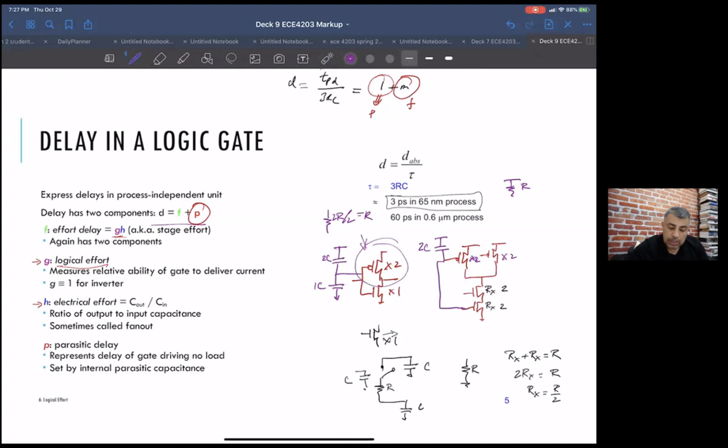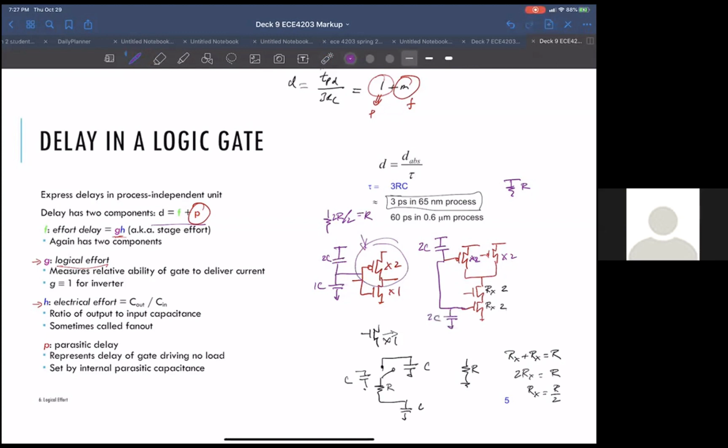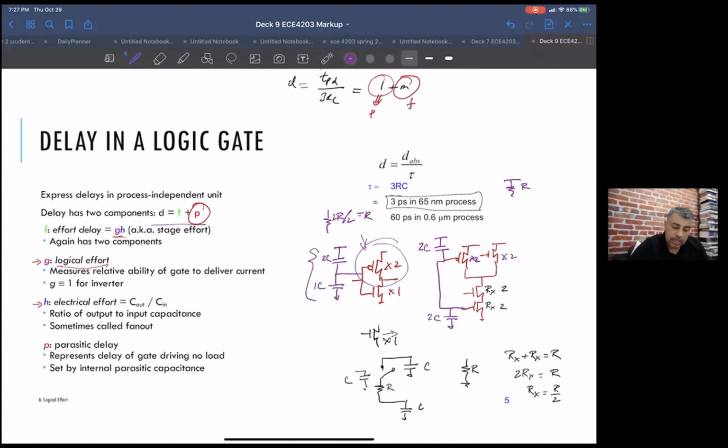And then what would be the capacitance of this N MOSFET? It's 1C here for a times 1, and we have a times 2. Will it also be 2C? It'll also be 2C. Okay. So the total gate capacitance here is 3C. The total here is 4C. Yeah. Okay. Thanks, Stephen. Thanks for being a good sport.